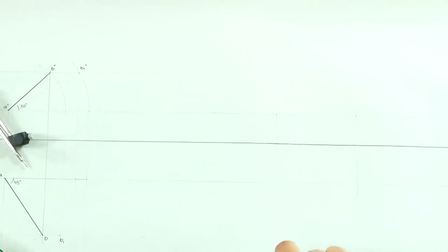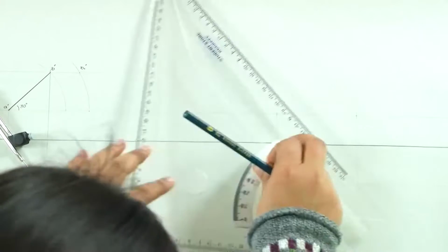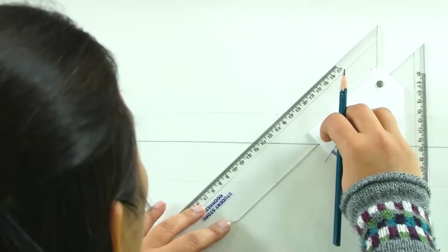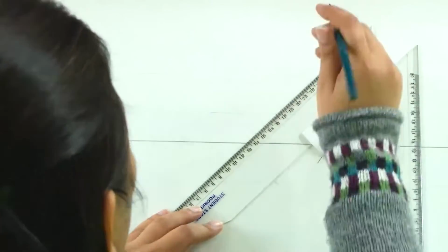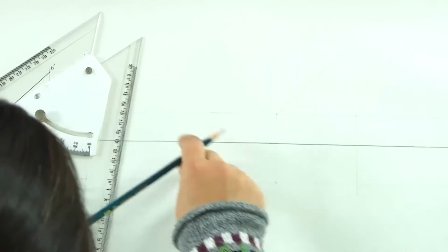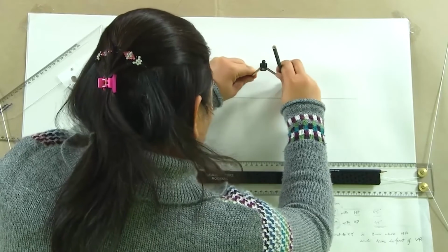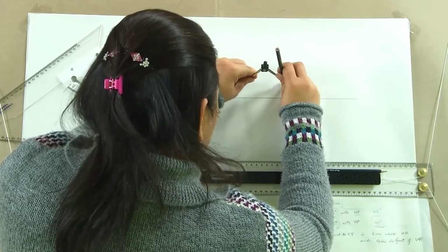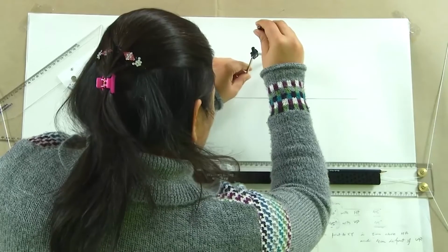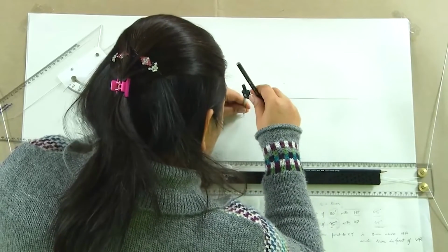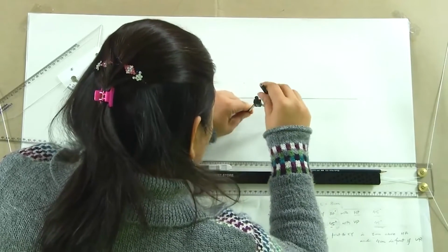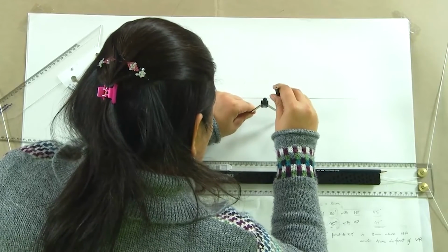Now, we have to incline it to both the planes at 45, assuming that it is parallel to one plane and at 45 degrees to the other. We will draw these lines at 45 degrees. Then we mark the length of 8 centimeters along this inclined line